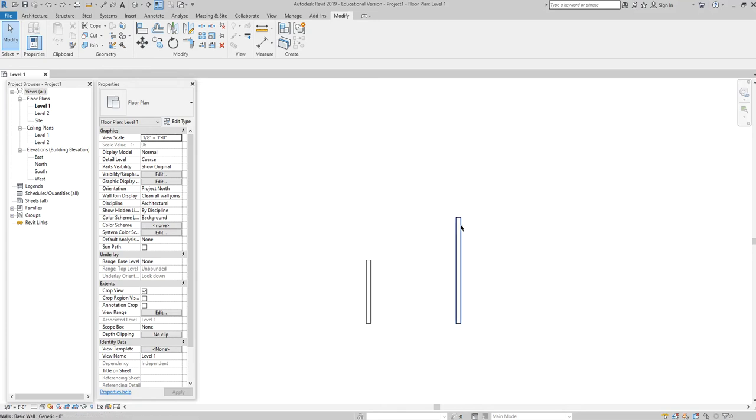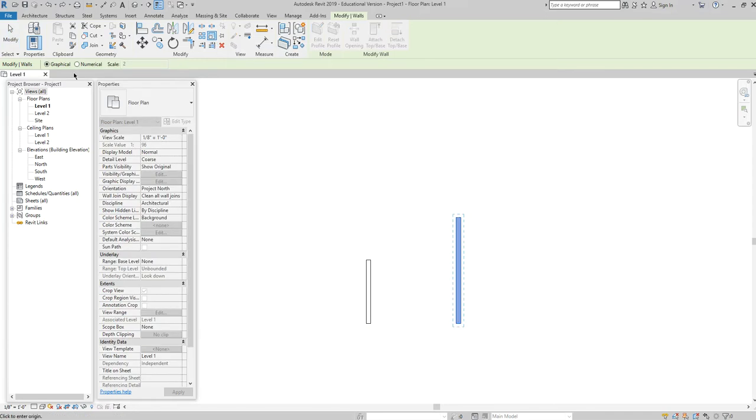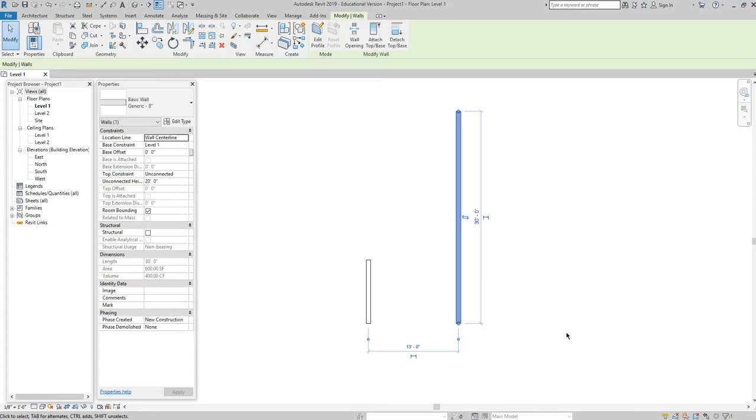Zoom out a little bit. I select the object, I click on scale, I'm going to choose numeric instead of graphic, and it says, okay, scale a factor of 2, great. Click to enter the origin of where the scale is going to happen. Do I want it to happen from here up, or from here down, or right from the center? So I'm going to click the bottom again, click, and it scaled it to twice the size.